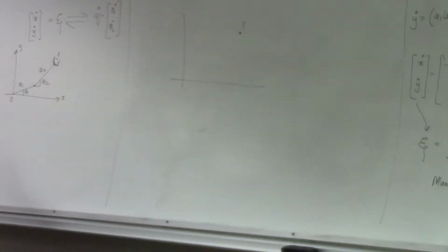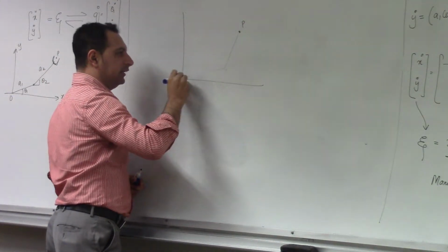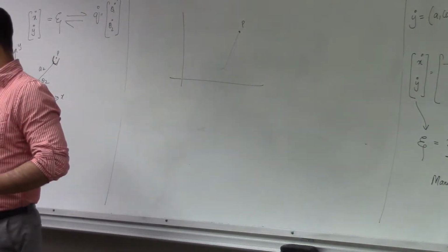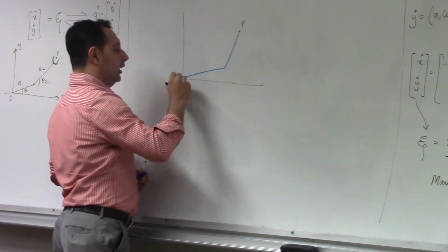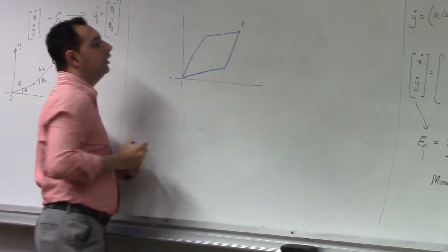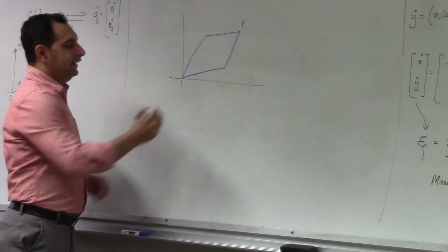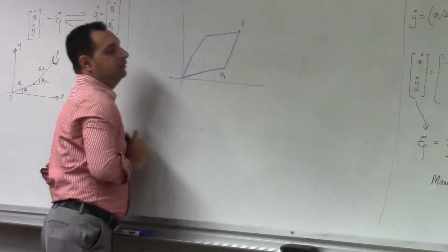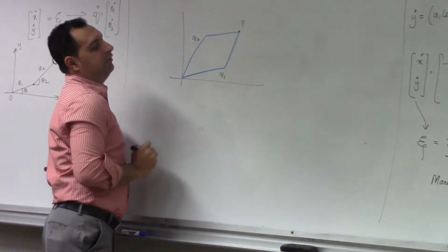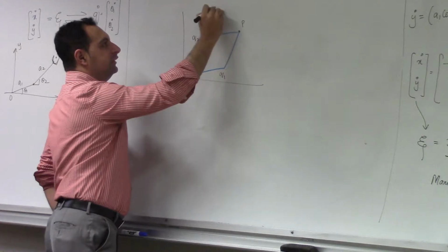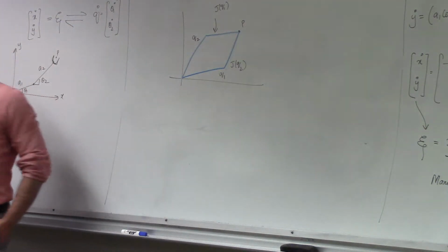Now I have a 2 degree of freedom manipulator. We have studied this already. I can reach this point in two postures like this. I can reach this point like this, and I can reach it like this, right? So this is my elbow up position, this is my elbow down position. Let's say that the joint values here are Q1. The joint values required to reach this point in this posture are Q2. So if I find the Jacobian here, in this case, J of Q1 and J of Q2, will they be the same or different?